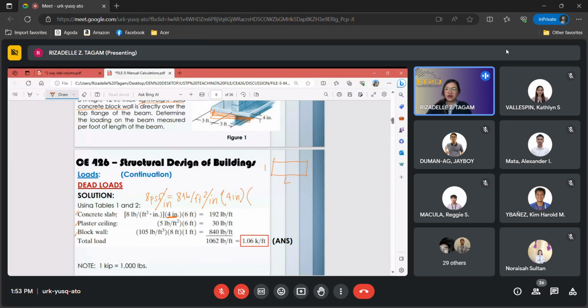This is our L and this is our W. Looking at our beam, there is the span. The tributary width we will use is this W, the width, so that part is the 6 feet, the opposite side of the span. Okay, Basil, are you confused? The L there, the span, is not what we put there. Instead, we use its partner, the width on the other side. So, 6 feet, because 6 feet is our tributary width.